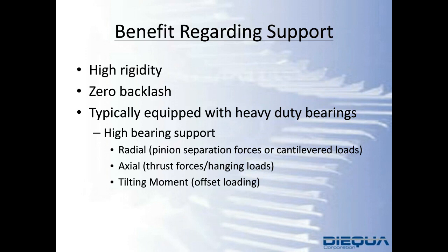Also, tilting capacities. We consider rigidity in two manners. We have tilting rigidity, right? While you are expecting the robot flange to have high bending and tilting capacities, you also expect it not to deflect. So it's one thing to support the loads, but another thing that it supports it while deflecting. So many times you consider angular rigidity. In this case, there's also the tilting rigidity.